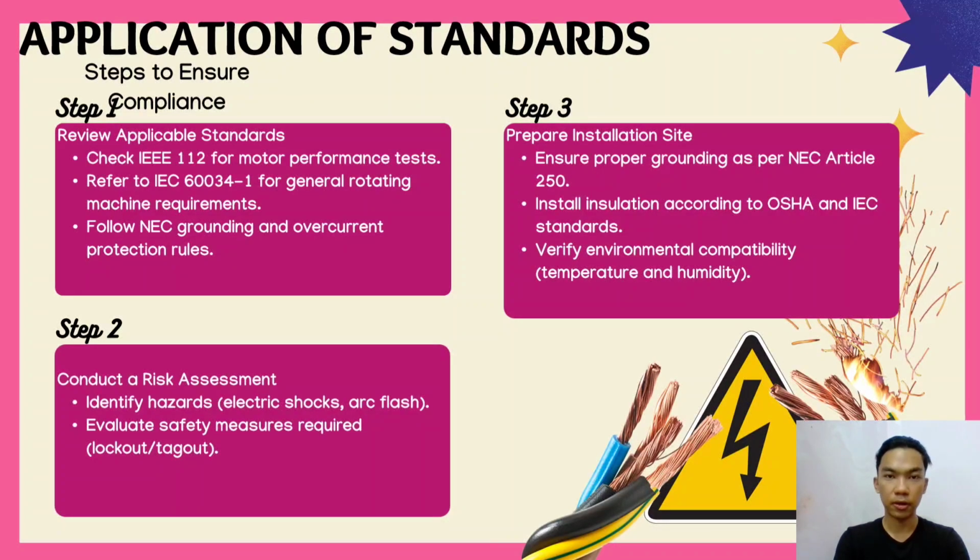Next, I'm going to talk about steps to ensure compliance. Step 1. The first step is to review the applicable standards. The engineer must check IEEE 112 for performance tests, refer to IEC 60034-1 for general requirements, and ensure it complies with NEC rules for grounding and overcurrent protection.